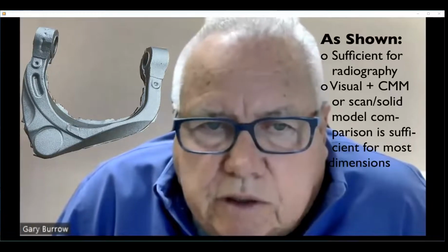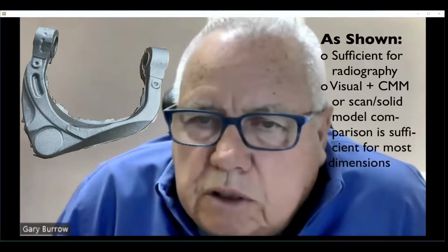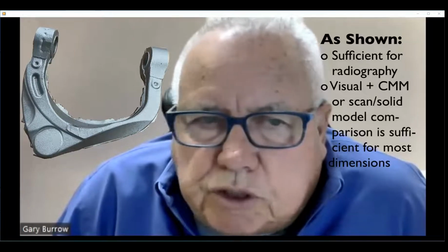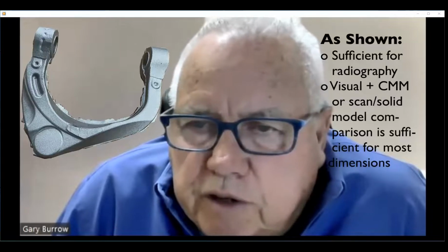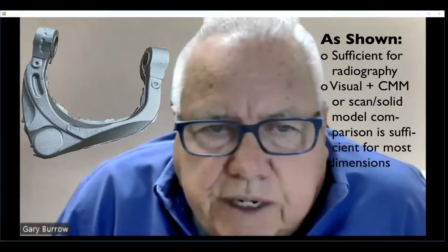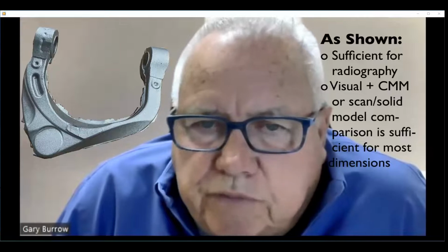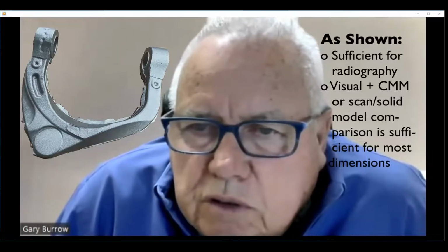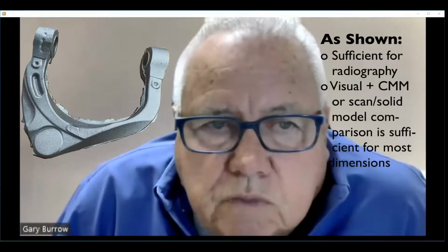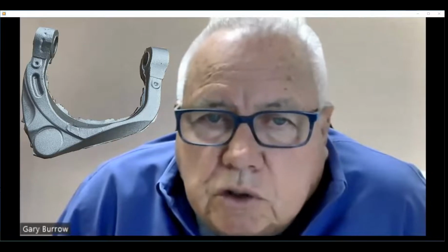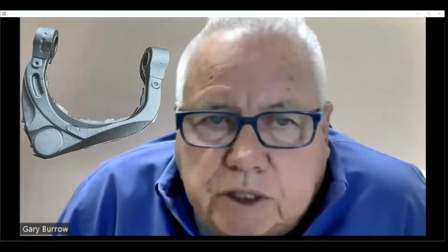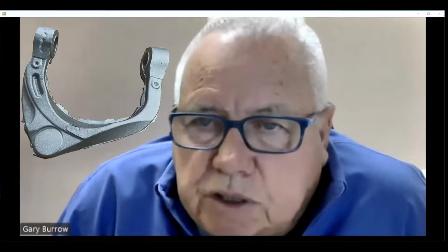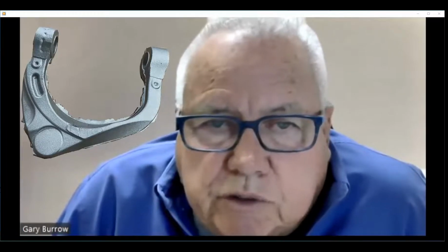Either scan them and compare them to the solid model digitally or use a CMM to check the most important dimensions. Now is the time to find pattern maker's contraction rate estimate errors, mold assembly variations, or others in the solid model. Occasionally, such quick AM prototypes are sufficient in solidification integrity, dimensional correctness, and surface finish, in that the prototypes can be added to the production quantity.